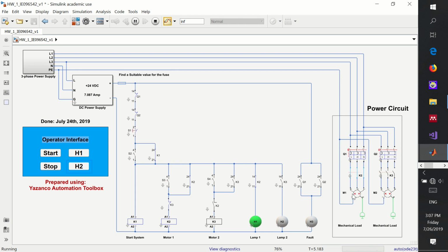So now we are hoping that the motor M1 is actually running. We cannot tell for sure, since we don't sense the current value or maybe the rotation speed of the motor. So the best we can tell so far is that the running conditions are met, but we cannot tell whether there is an actual running of the motor or not, until we use the appropriate sensors.